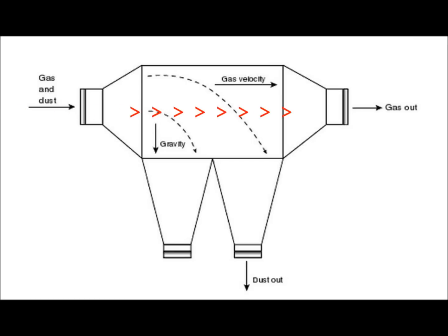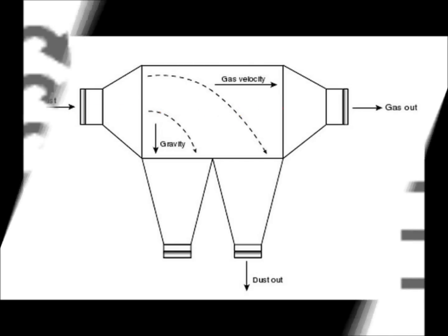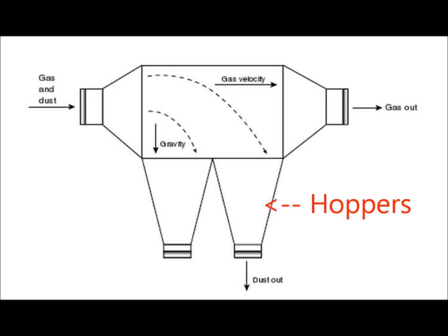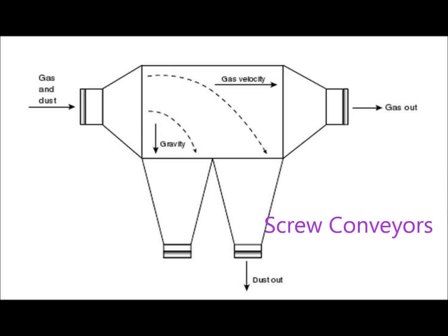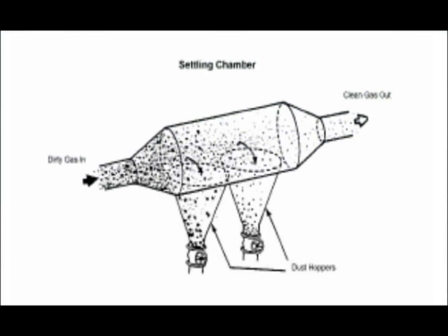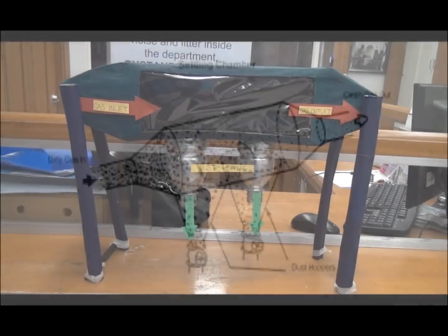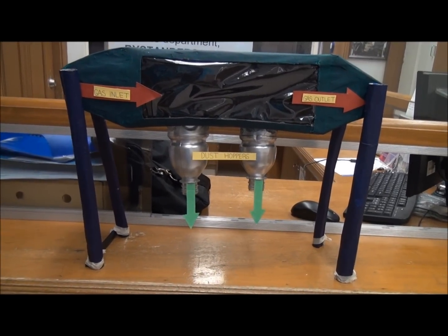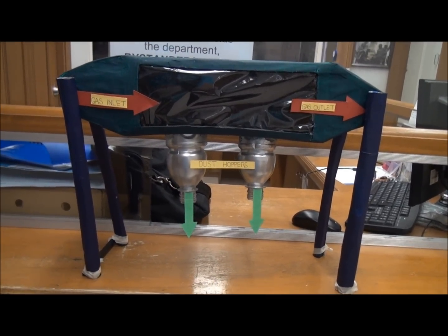Flow within the chamber must be uniform and without any macroscopic mixing. Uniform flow can be improved by employing flow straighteners at the inlet to the chamber. Hoppers are used to collect the settled out material, though drag scrapers and screw conveyors have also been employed. The dust removal system must be sealed to prevent air from leaking into the chamber, which causes turbulence, causes dust reentrainment, and prevents dust from being properly discharged from the device.